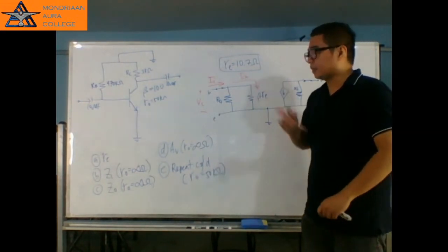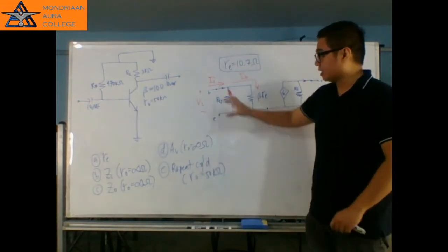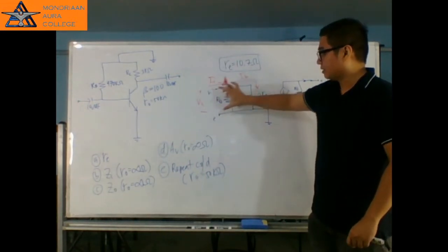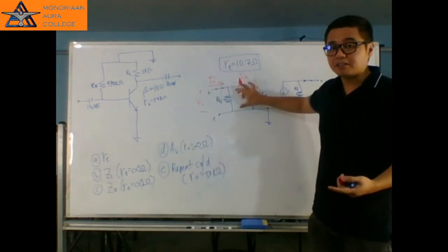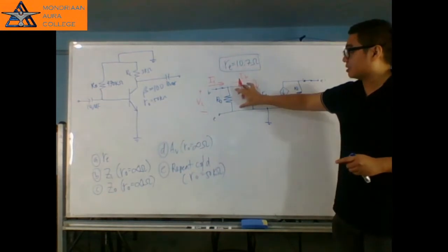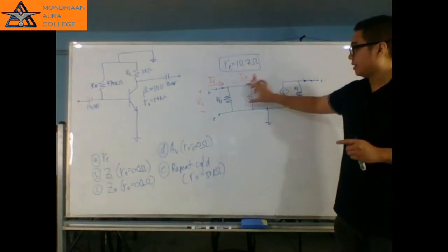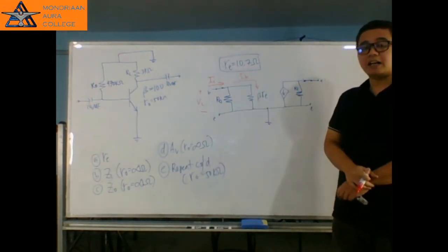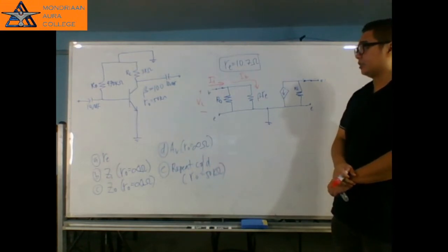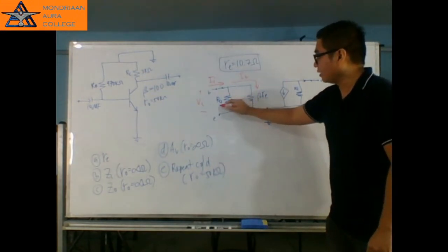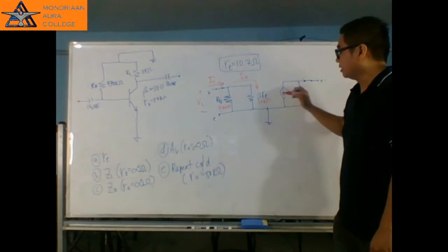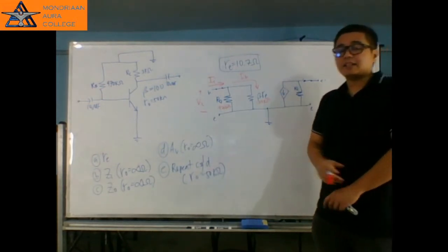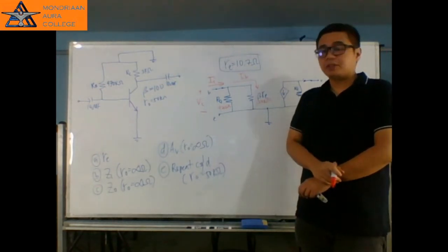Right? What is the voltage across R sub B? Since ito yung V sub I natin, kung mapapansin natin, no, yan din yung ina-apply sa R sub B. And at the same time, that's the same voltage or signal that's being applied to beta R sub E. So, lagyan lang natin labels. No? So, we have 470 kilo ohms. And then we have 1.07 kilo ohms.